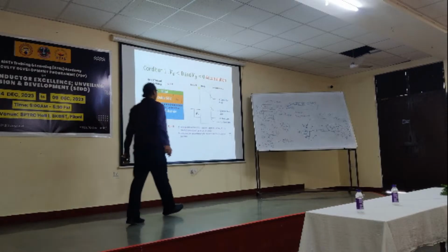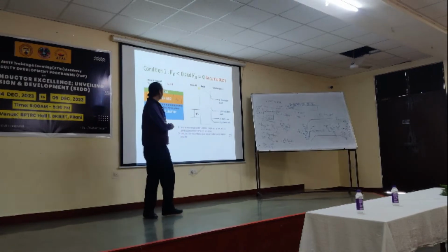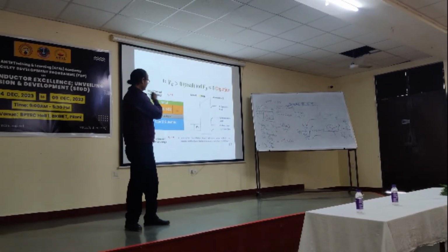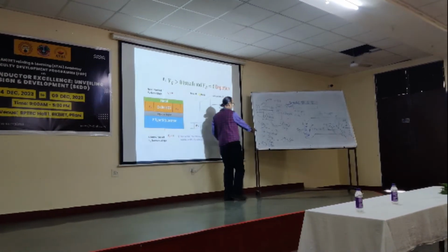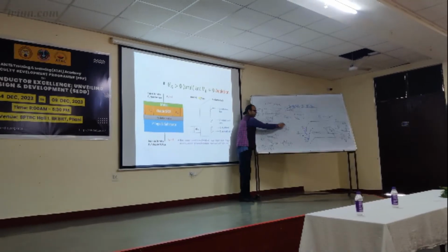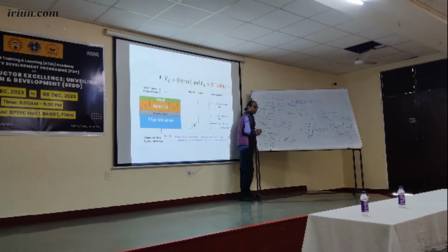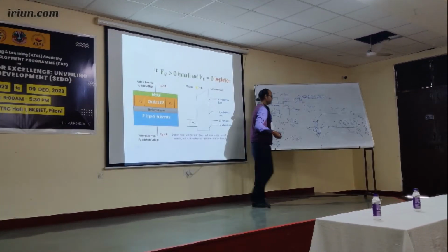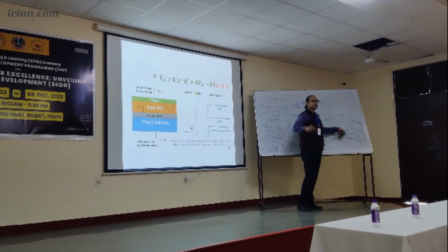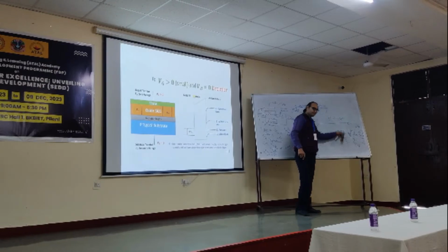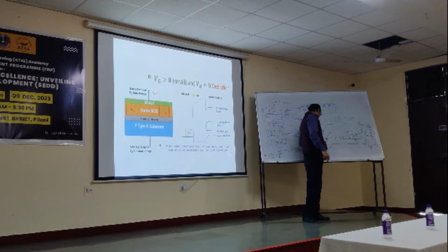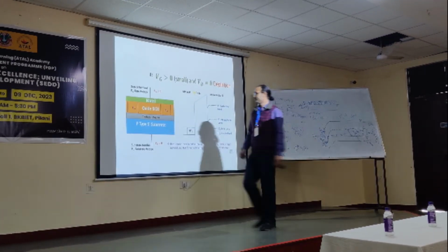And as I said, Fermi levels have to be aligned. Then now I have started applying this voltage. I am here. Flat band is made. Now I want to deplete it. How much voltage? Phi F up to here, and further we have to apply phi F more. So twice phi F. Okay.